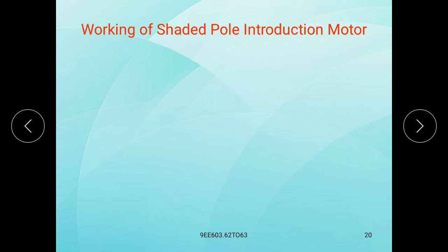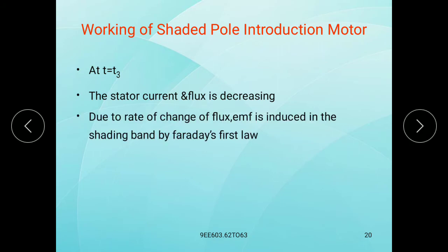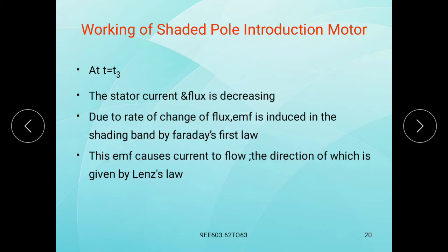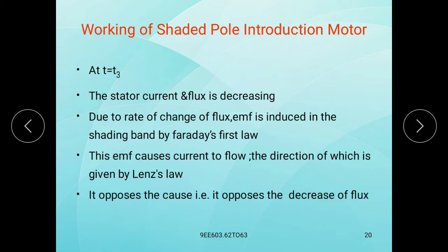Now at t is equal to t3, the stator current and flux are decreasing, so due to the rate of change of flux, EMF is induced in the shading band by Faraday's first law. The EMF causes current to flow, the direction of which is given by Lenz's law. It opposes the cause of its production, that is, it opposes the decrease of flux.